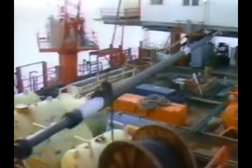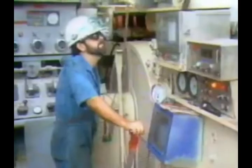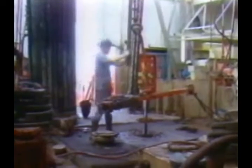The procedure for running a tubing conveyed perforating system is as follows. First, the guns are assembled vertically in the derrick. Followed by the firing head, or heads if a backup system is used. Next, the vent or production valve.